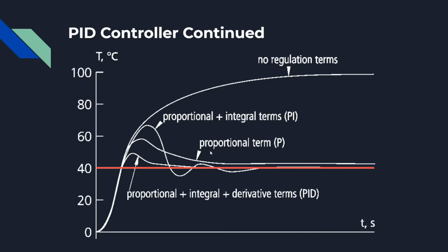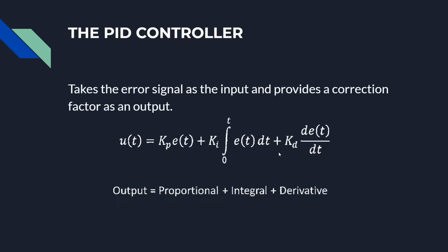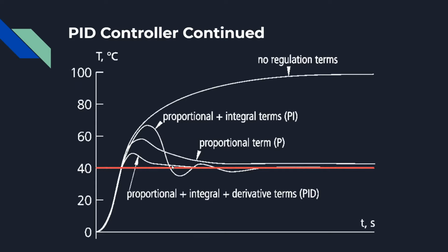The first type of controller we could do is the proportional controller, which would just be Kp, some constant, times that error. Right at the beginning, there's an error of 40 degrees because we started at 0 degrees Celsius. So we see there is some error, so the microwave would be on, and we'd increase the temperature of the microwave so that it heats up fast.